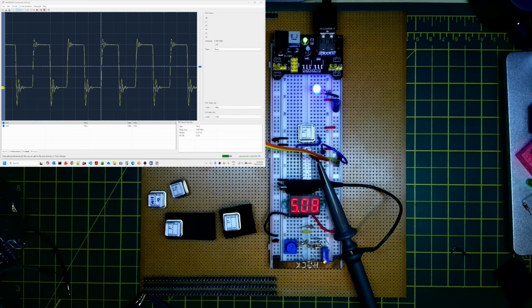So we've covered the AND, OR, exclusive OR and buffer gates, and we've also seen that when we shove higher frequency signals down the bus rails here, then in fact there's not an inconsiderable amount of ringing and overshoot on some of the signals. And in fact, when we were dealing with the 40 MHz signal, the overshoot here for 40 MHz was getting to over -2 volts.